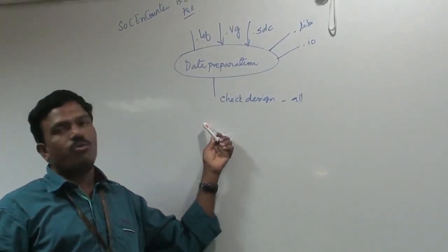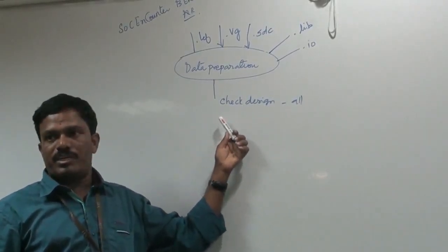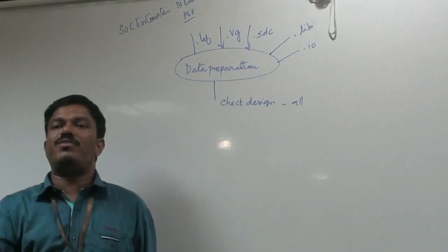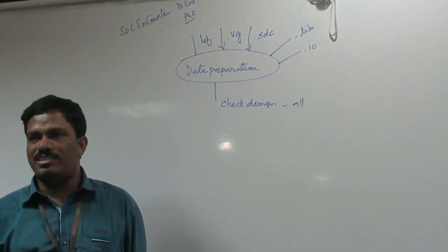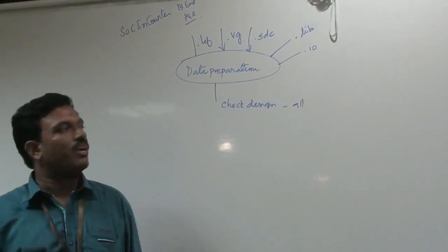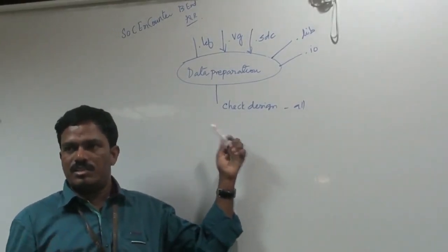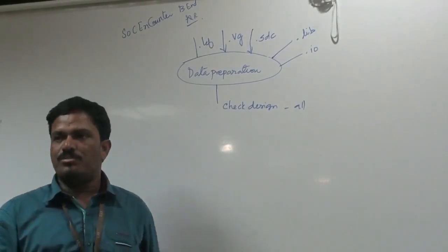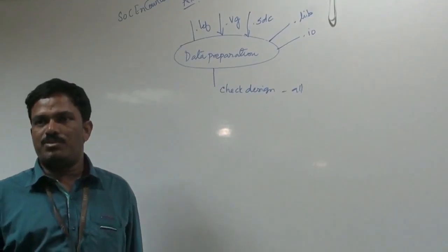And also we are going for unified design. That unified design says the component, right, we should not use the same component in different places. Each and every module needs to have a different instance name, right? So everything we have to confirm in the initial stage, that is called check design -R. This will give you the approximate area, approximate power required, approximate timing required, right?